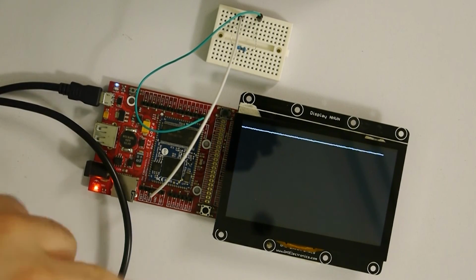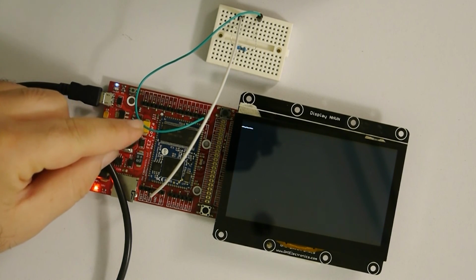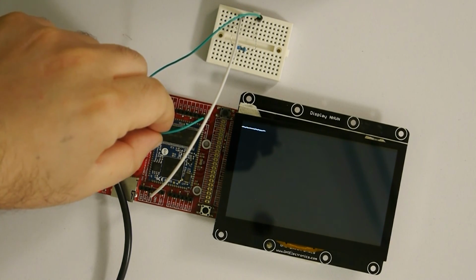So in this example over here, our program internally is turning the signal high on this signal right here on the green wire. It's coming on for a short time, or you can set that in the code. And then after it sets it on, it makes that pin an input. It releases it. And then that pin is going to discharge over time.